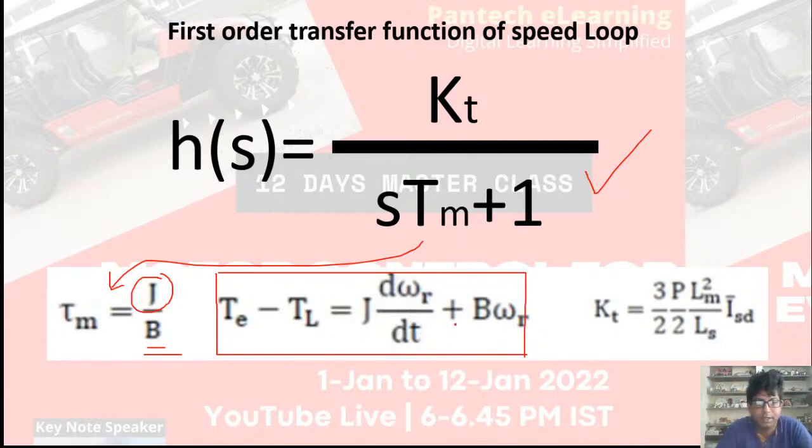That's the first order differential equation, and here one KT is used, that is the value of KT, 3 by 2 into P by 2 into Lm square by Ls into ISD. Already this we know, it is fixed. This is for constant flux, so we know what that is. So KT will be obtained, and this Tm also will be obtained, and again the same way.